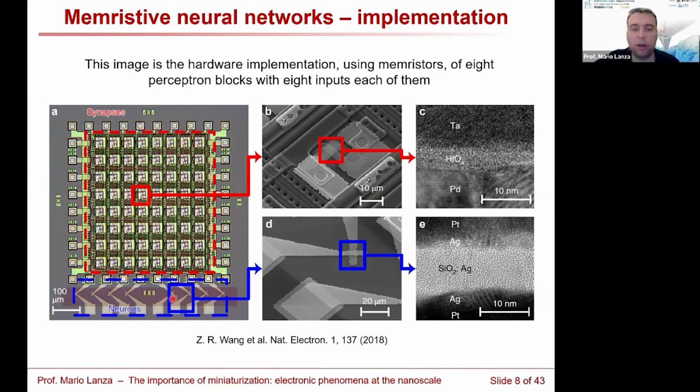Actually, the authors here also fabricated one electronic neuron by using one memristor with silver electrodes that shows volatile resistive switching. So it's the threshold type resistive switching. And with this, they can activate an output when the current across the column surpasses one specific value. So this was another application.